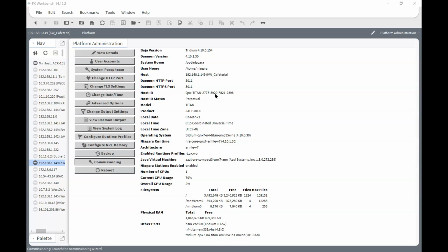When you get to this screen, you're going to see all the versions that are installed right now on this JACE. The available versions are right here, depending on what you're running and what this JACE is actually licensed for. So what you're going to do is just come down here, hit upgrade all out of date. Nothing's going to happen other than it's going to gray out everything. You're not going to see everything upgrade instantly, so don't get alarmed if you don't see all this update or anything. It's going to now update every single module that is on this JACE to the latest version that you are licensed for. Once you hit next,